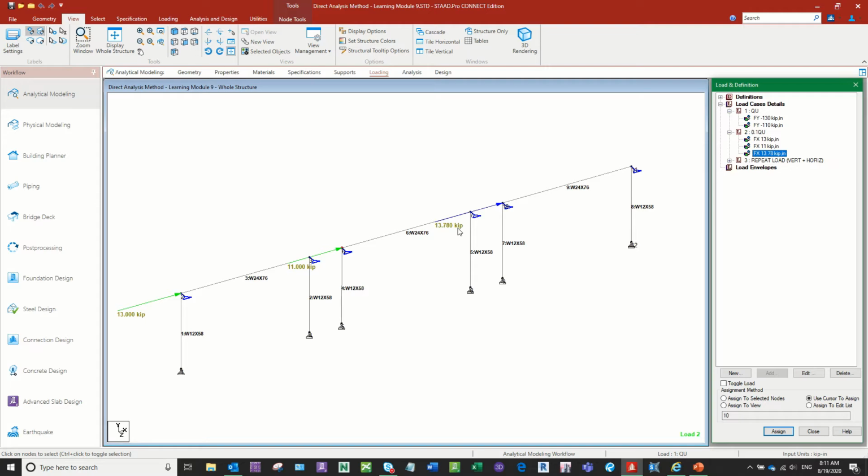And you would get 0.39. Multiply that by 2 to account for two loads. You have 0.78, and you add that to a 10% lateral load that is just part of this example to begin with, and you have 13.78. That's where we get that number from.